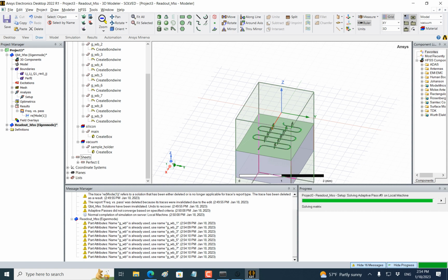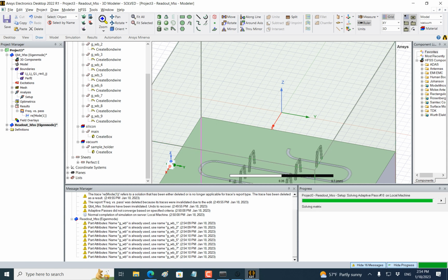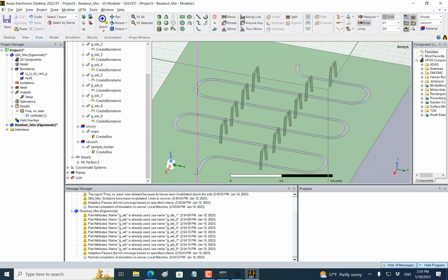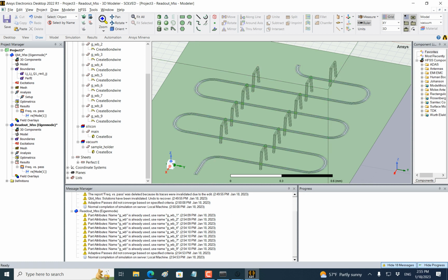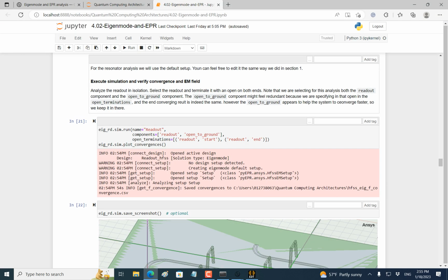But obviously, you see that it creates a new structure, and this is the coplanar waveguide. You press shift and then drag your mouse, then it will move around. Control plus, you will zoom in. Okay, so let's look at this, right? And you have this. It is actually necessary in reality to avoid spurious solutions, to have an equalized potential. I won't go into details on this, but this is something it generates automatically.